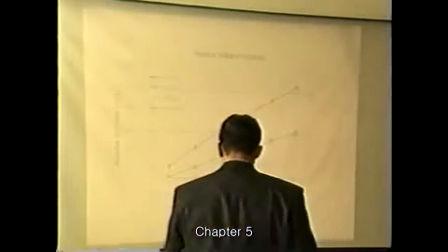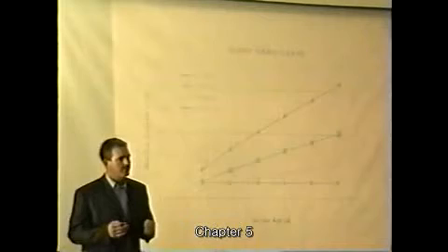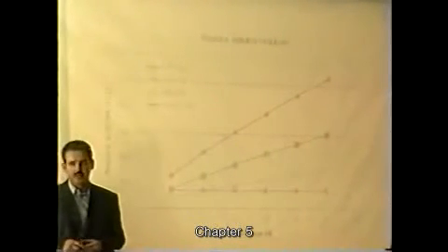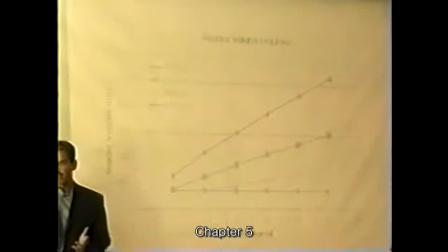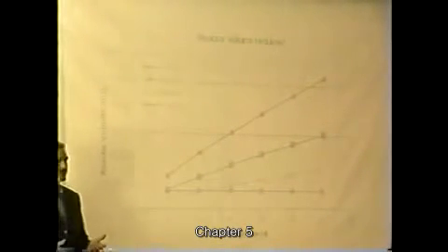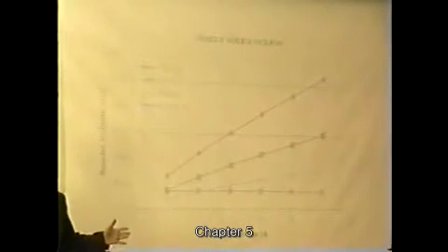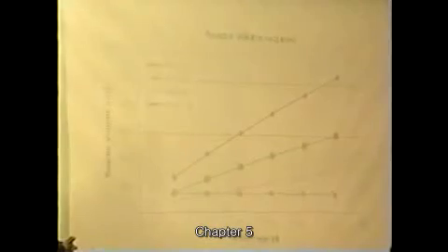This is rather interesting. An activated sludge system, if you do the numbers, and the way I do it is the modified or UCT model, you can calculate based on the volumes you want to treat and the amount of COD you have to remove how big a reactor you need. That's a given for a certain sludge age.